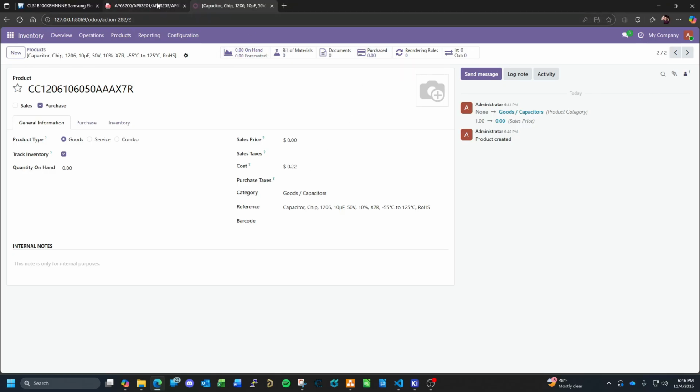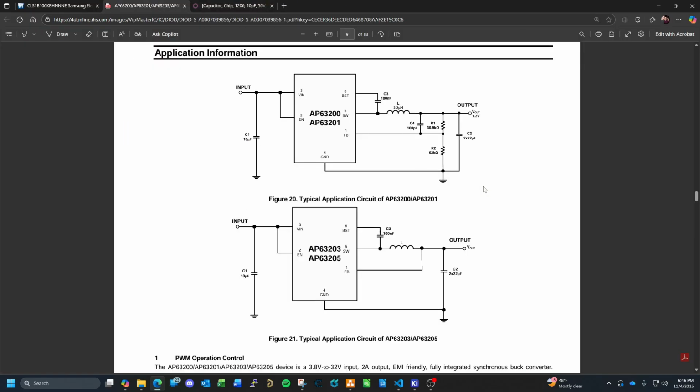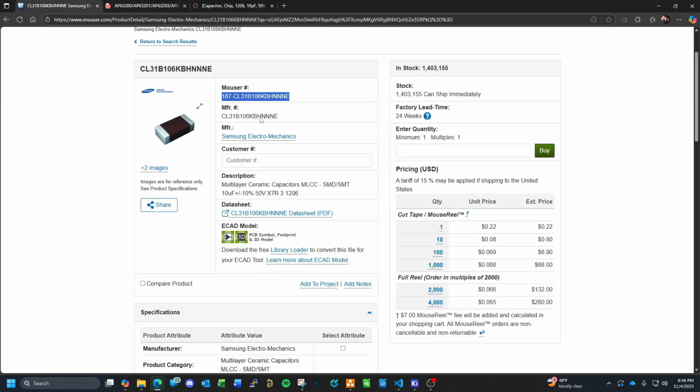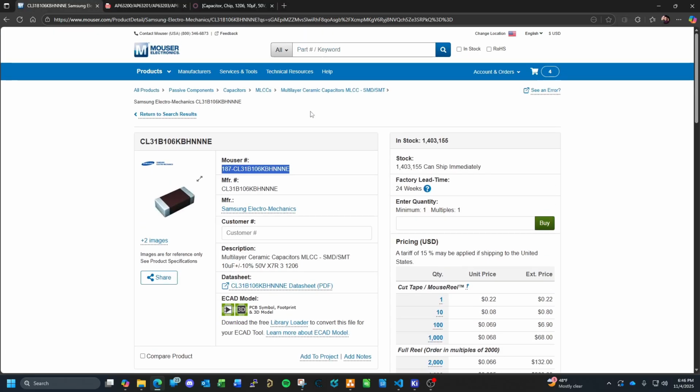So let's go and close out the DigiKey. We can add them as a supplier later. 100 nanofarad. That's a 104 capacitor. One thing to keep note: those things you will use like water. In manufacturing, we would buy those things 10, 20 reels at a time. That's how often you'll use a 100 nanofarad. They're very commonly used. So let's go back to here.